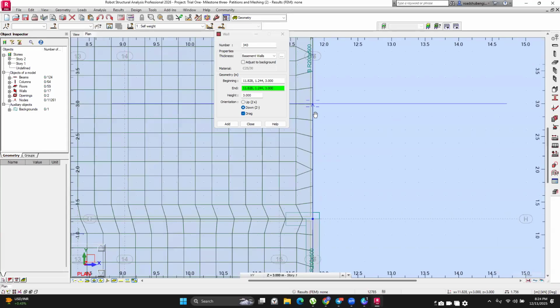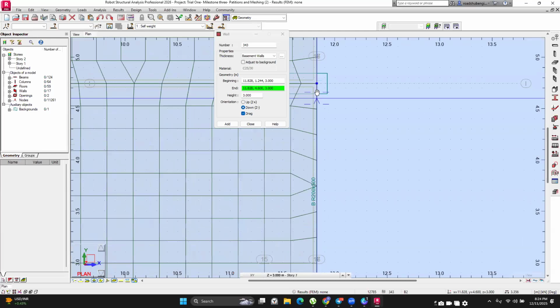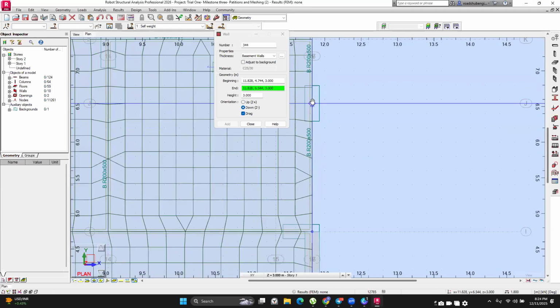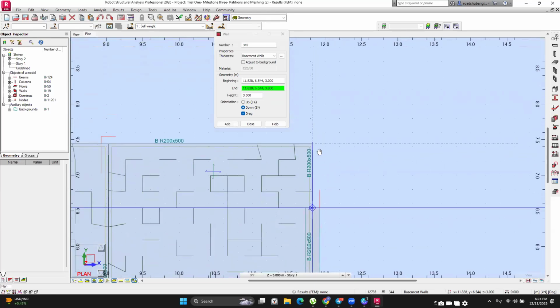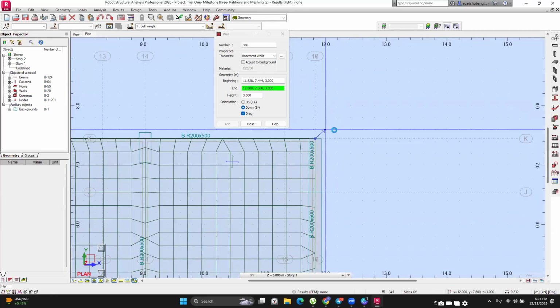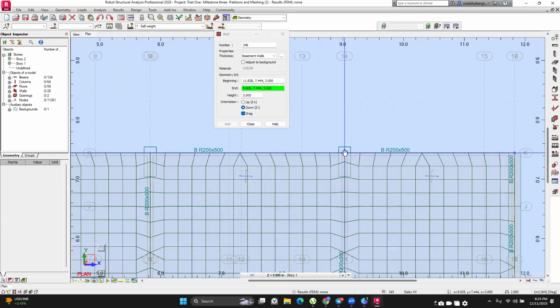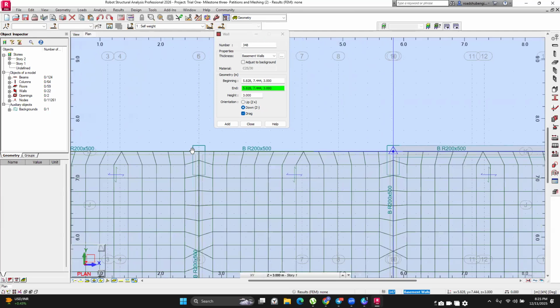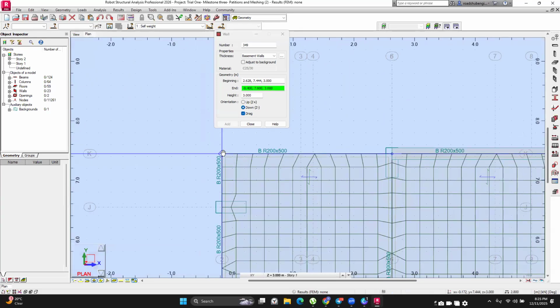If you place your walls to the face of the column, they are not going to be considered. So just to be safe, ensure you model them to the center of the column, turn on drag, and proceed all the way to the end. Once you are at the top, just continue modeling throughout the entire outer perimeter of the structure. Continue clicking on the nodes.